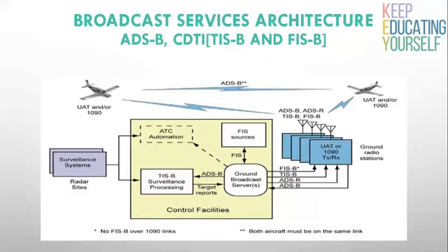Flight Information Service Broadcast, FIS-B. FIS-B is a free service available to aircraft that can receive data over 978 MHz UAT. FIS-B automatically transmits a wide range of weather products with national and regional focus to all equipped aircraft. Having current weather and aeronautical information in the cockpit helps pilots plan safer and more efficient flight paths, as well as make strategic decisions during flight to avoid potentially hazardous developing weather.